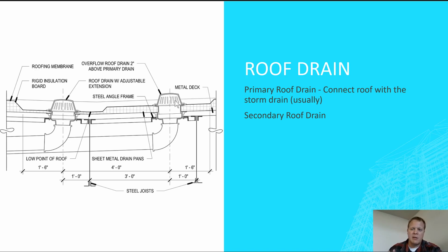But one of the things I want to talk about from a coordination standpoint is, imagine your building and what has to be done. Think through this sequence, right? You're going to build up, floor by floor, or maybe it's only a single story, right? Well, these drains have to be in before you can connect them to pipe, and the roof has to be on before you can really make these drains useful. The drains have to be in and the roof has to be on and tied in before the roof drain is useful.